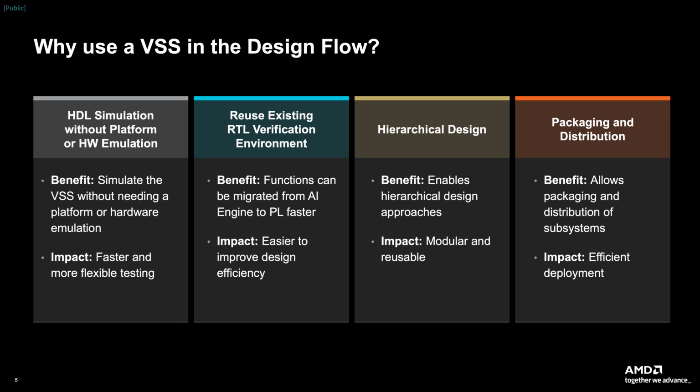Migrating functions from the PL region to AI engine tiles is also faster since existing RTL verification environments can now be reused. Faster migration allows for deeper exploration of AI engine tiles for functions, potentially resulting in more efficient designs. Support for VSS hierarchy also allows for intuitive, RTL-like modular design. The resulting VSS component can be deployed like traditional IPs.